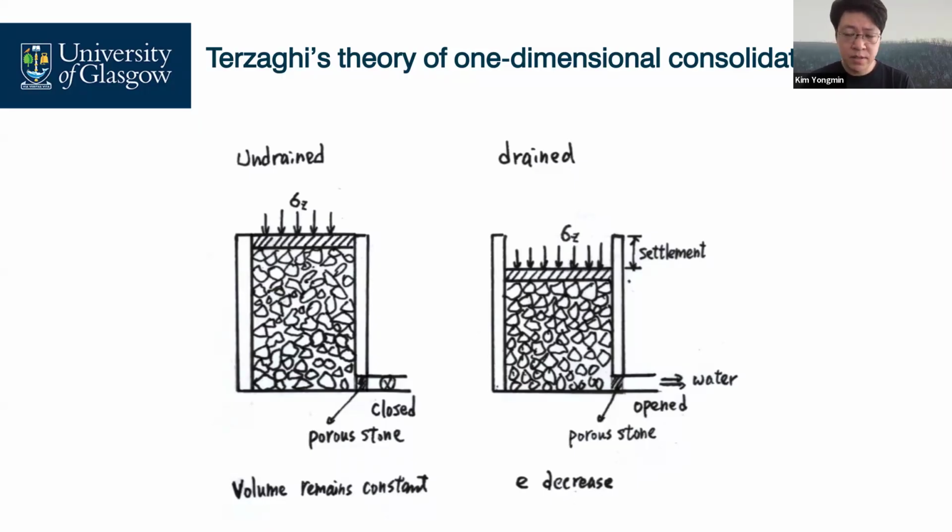That's quite a short period. In a short period, can water drain out, do you think? No. Of course, a little water tries to drain out as a natural phenomenon, but after installation of your pile, we take it all out. So in this case, we consider it as undrained.